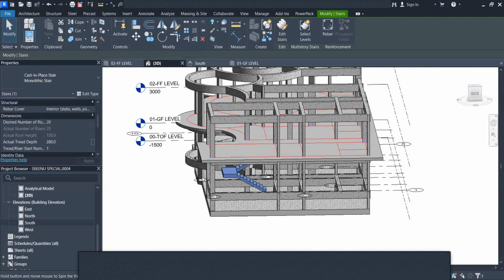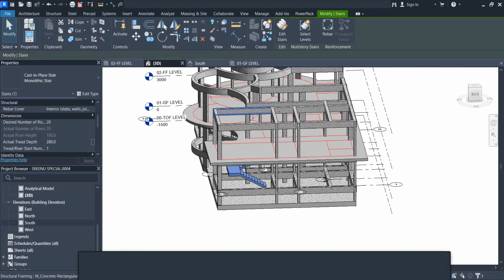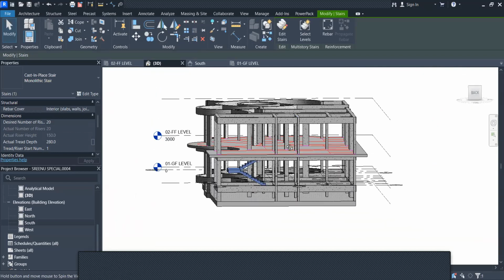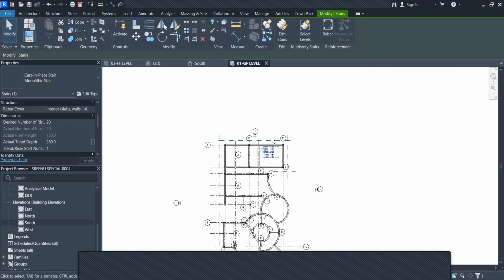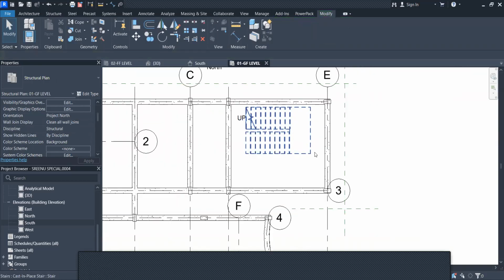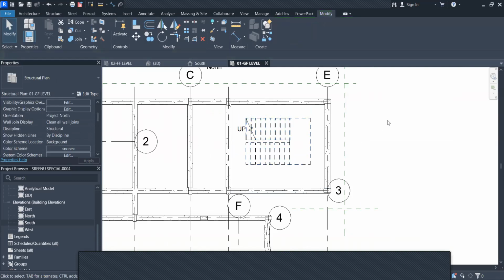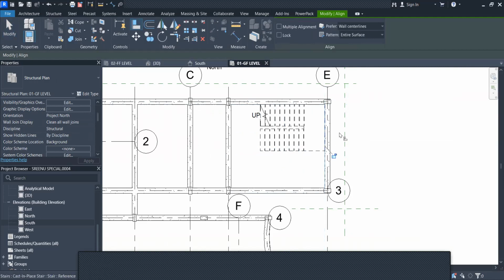So now let's create an opening here before we copy the stair maybe upward there, because I think we have another level there. Oh no, actually is this a floor? Let's create an opening here. So I'll go there and you see that this is the stair. Remember, if you want to move this stair, I can select on it. I can use my arrow on the keyboard. I can use align now, AL. If I want to align it there, I'll just click there. Or if I want to align it here, click there and there, you can align it.